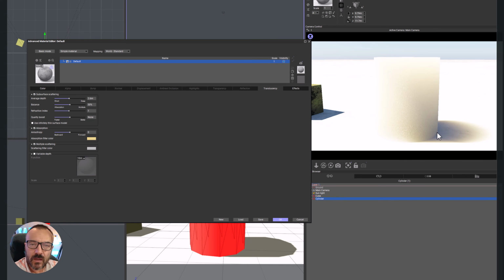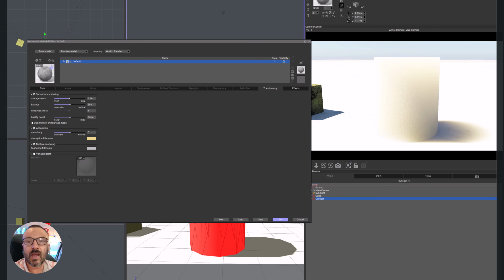The main problem with this is, first, it will take a long time to render because it needs to generate all of those rays as they're coming, splitting around and everything. So it takes quite a bit of render time. But besides that, you may have a problem. If your quality is low, you'll have grain. Grain is happening because, just imagine, like before with mirroring, the application will only generate so many steps. And the reason is you don't want to generate forever or it takes too many resources.